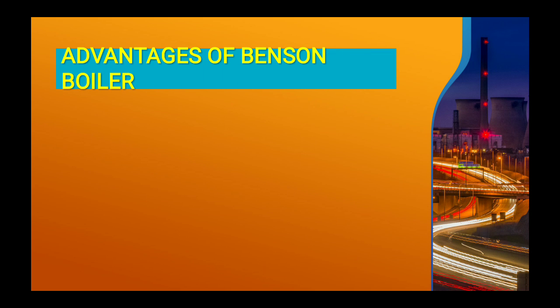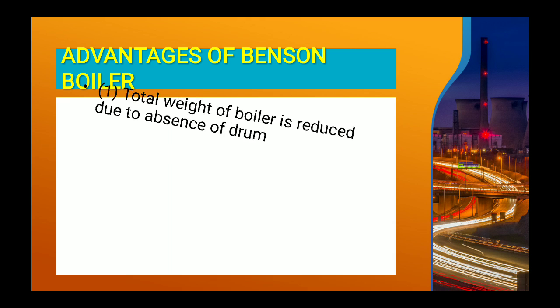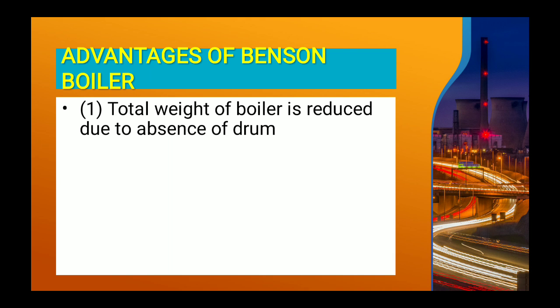Now the next one is the advantages of the Benson boiler. Number one, the total weight of the boiler is reduced due to the absence of a drum. There is no boiler drum provided, so it is much less in weight. Number two, low cost of transport.